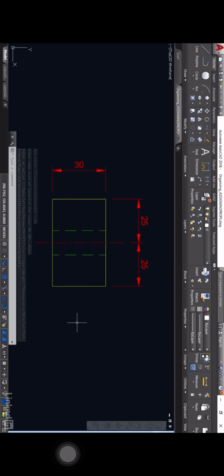So as you can see, you can assign properties by layer using the layer color, line weight, line type, or you can do it individually on an object by object basis instead of adopting the properties of the layer the object is on.